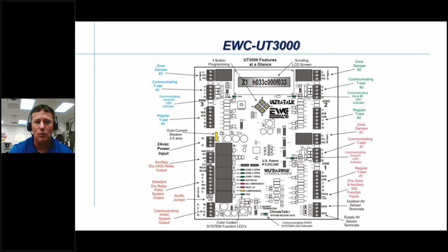So we have a zone board where we can use multiple thermostats, and we can get away from those expensive proprietary manufacturers' communicating thermostats. Because if I have a communicating Carrier system, I have communicating Carrier thermostats in every zone. And so with the Amana guys, when these Amana dealers go out and bid jobs communicating systems, they are just tearing up the market, because now they can go back to legacy wired zone controlling. And then they can even upgrade into like Jackson style zone controlling.